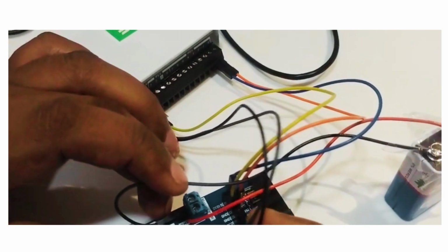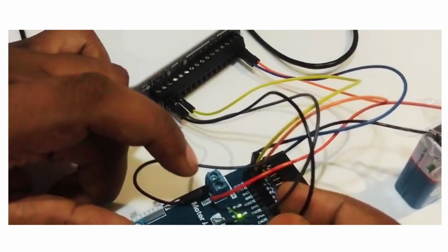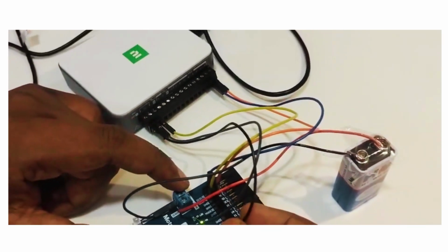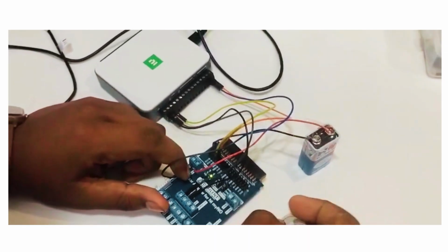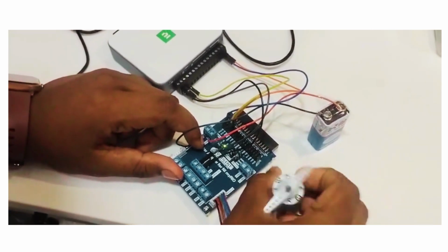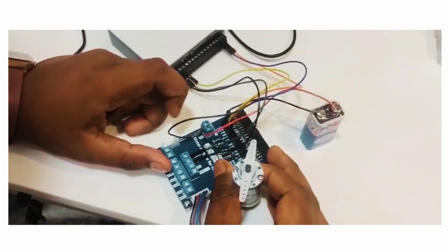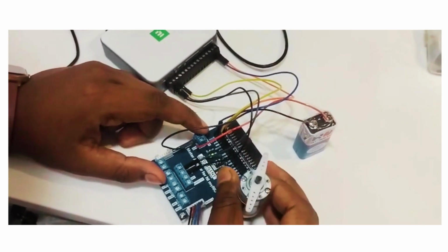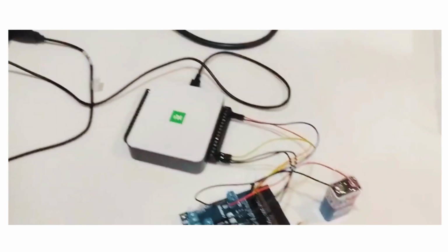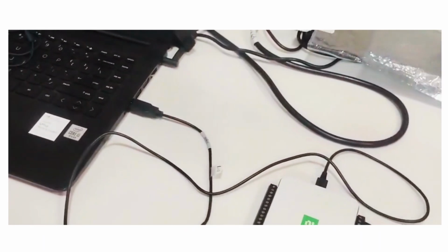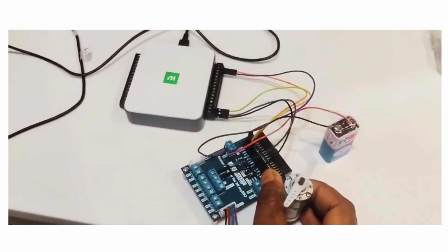And these two wires, the black and this wire, this black wire is ground terminal, and this is the 5 volt terminal power voltage, and this point gets the motor power that is required for this motor to rotate, and this required power is 9 to 16 volt. Here we provide the 9 volt battery DC power voltage. So we put this NI USB DAQ and connect it to the laptop. So again we run this program for this demonstration.